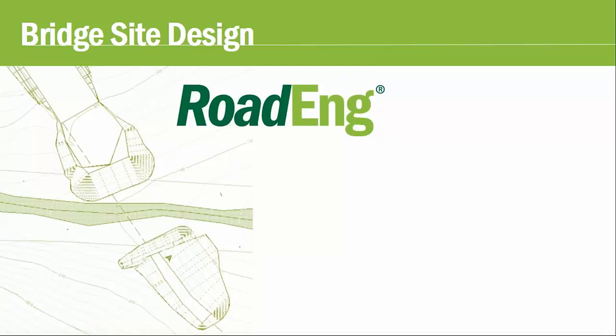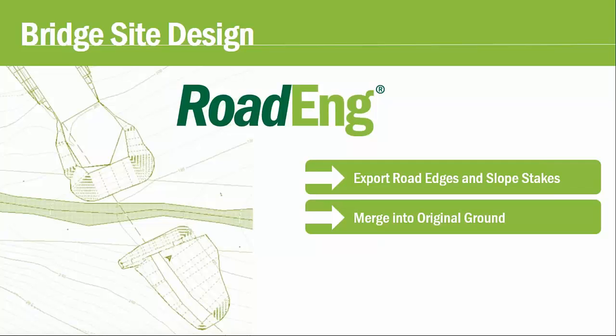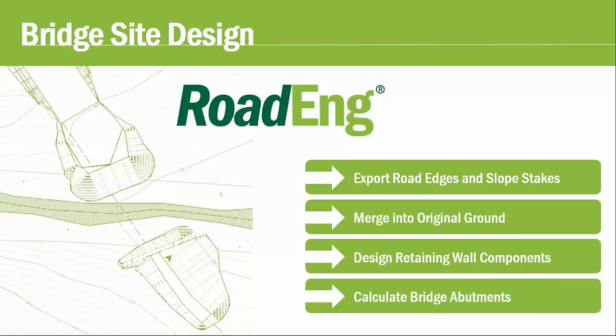We've already done the survey data import, the initial terrain modeling, and our road alignment behind the scenes. Jack has already applied a no-cut, no-fill template across where our bridge span will go. And he's going to be picking up from that point. The first thing he's going to be doing in our location module is exporting the road edges and the slope stakes, bringing those back into terrain to merge into our original ground, designing the retaining wall components, and then calculating the earthwork for our bridge abutments.